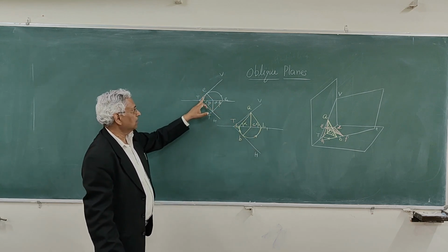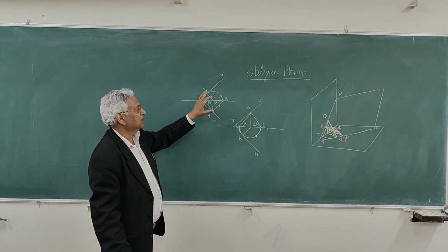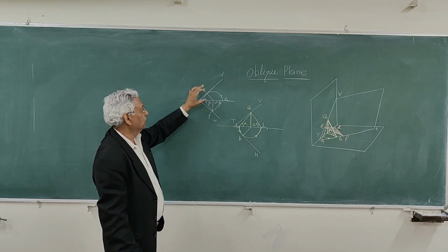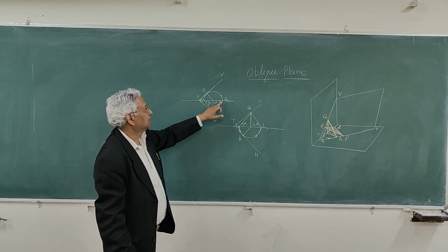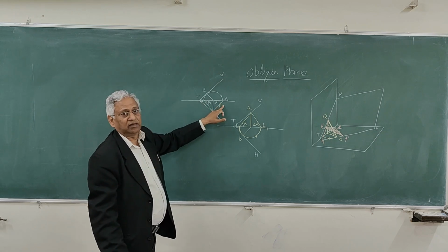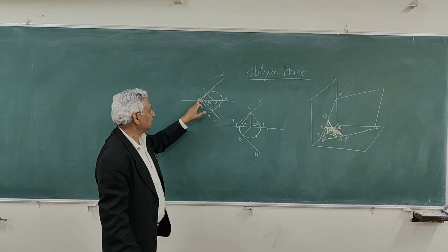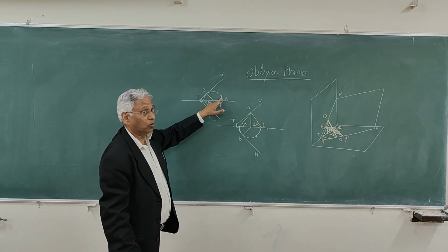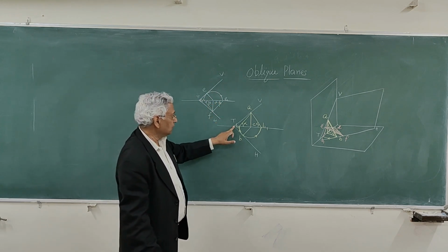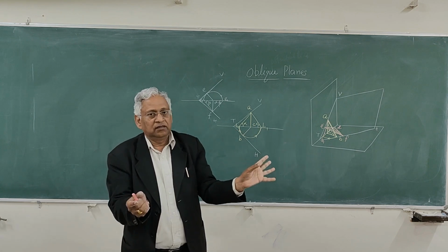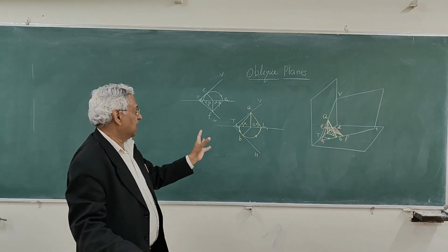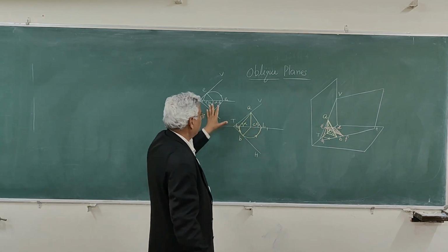Similarly, this is another half cone which you have placed in the vertical plane, and the plan is a triangle. The vertical trace is tangential to one cone, and the horizontal trace is tangential to the other. These two cones have different base diameters.